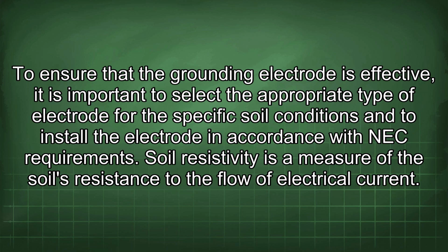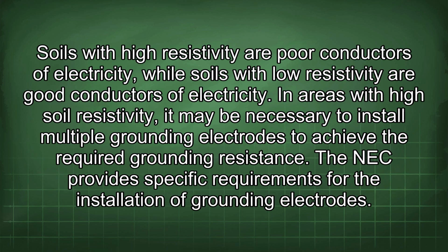Soil resistivity is a measure of the soil's resistance to the flow of electrical current. Soils with high resistivity are poor conductors of electricity, while soils with low resistivity are good conductors of electricity. In areas with high soil resistivity, it may be necessary to install multiple grounding electrodes to achieve the required grounding resistance. The NEC provides specific requirements for the installation of grounding electrodes.